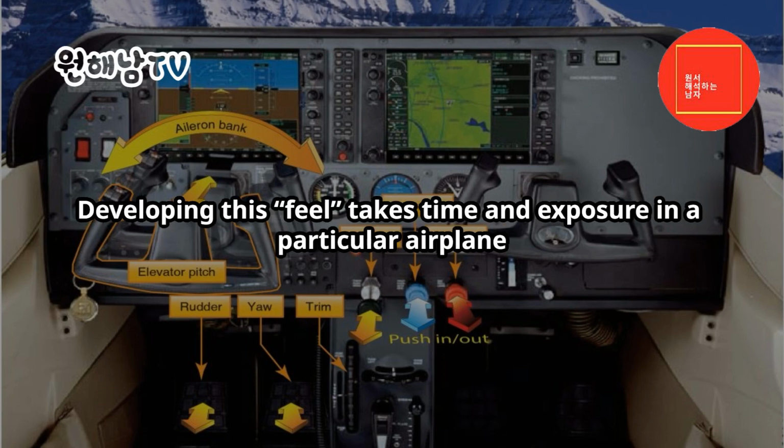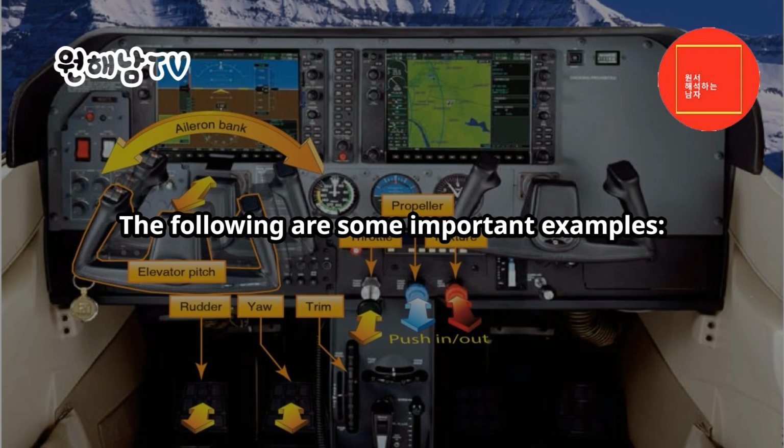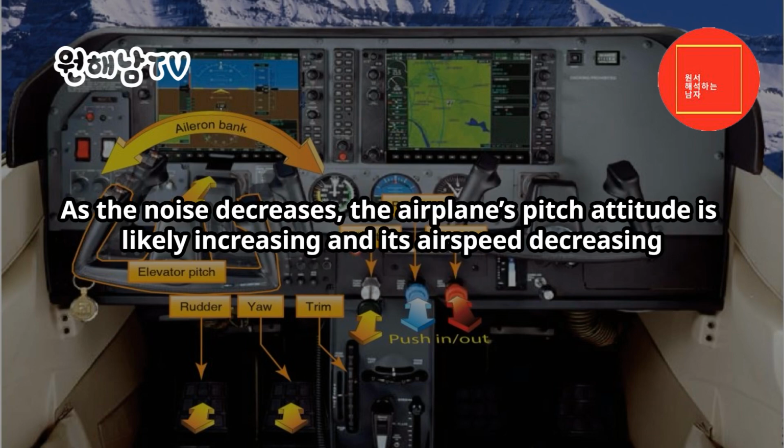Developing this feel takes time and exposure in a particular airplane. It only comes with dedicated practice at the various flight conditions so that a pilot's senses are trained by the sounds, vibrations, and forces produced by the airplane. The following are some important examples. Rushing air creates a distinctive noise pattern, and as the level of sound increases, it likely indicates that the airplane's airspeed is increasing and that the pitch attitude is decreasing. As the noise decreases, the airplane's pitch attitude is likely increasing and its airspeed decreasing.